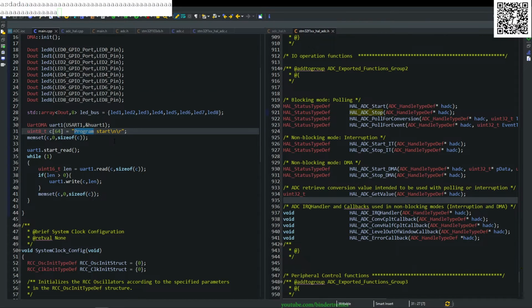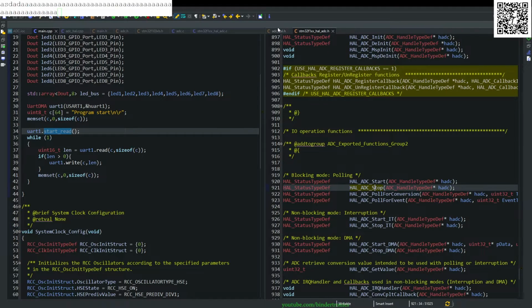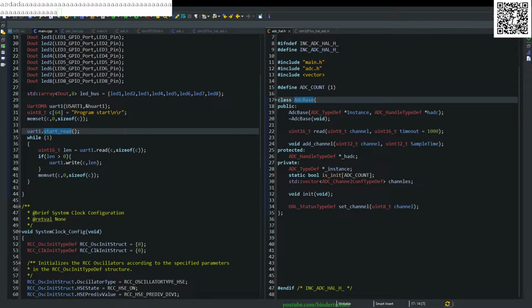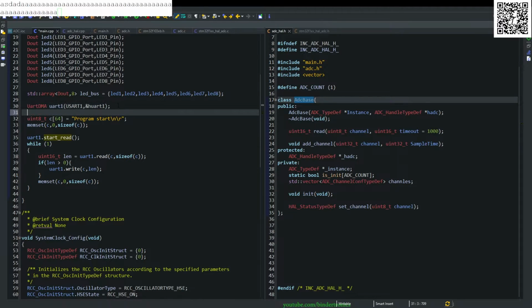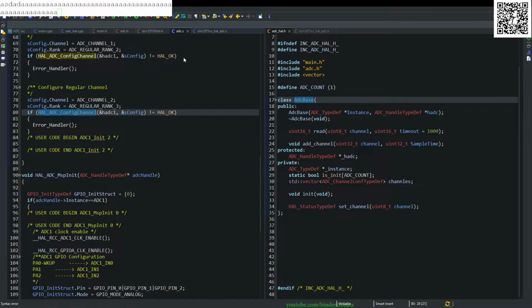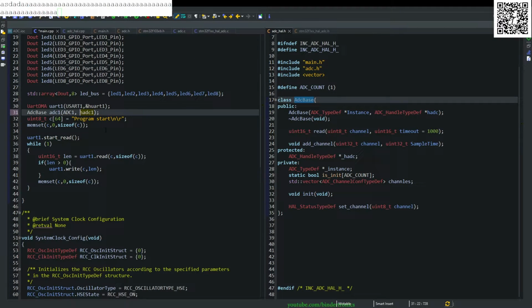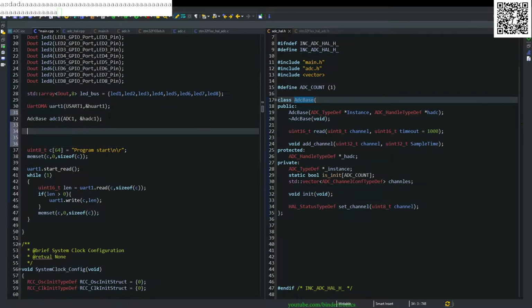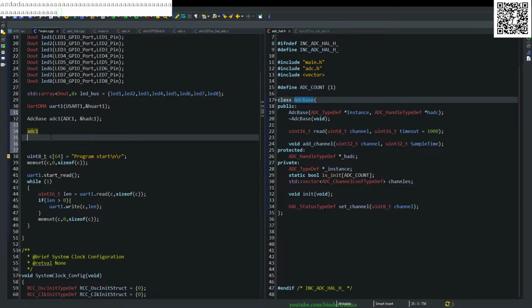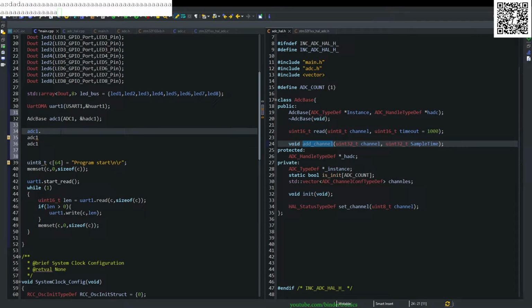So for our main program, we need to initialize our ADC. We have our ADC base. Let's put this after the UART init. Then we just say ADC1, and our constructor is going to contain ADC1 as the instance, and then Control Shift Tab, and this is going to be our instance reference. So in effect, exactly the same as the UART. So our ADC1, since we're using 3 channels, we are going to add 3 channels. And we just copy this over.